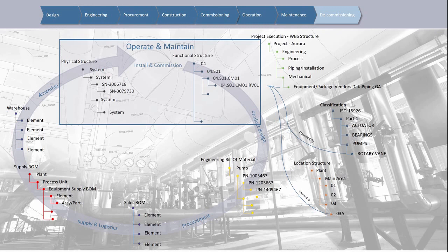Each product delivery undergoes mechanical completion tests to make sure it fulfills the requirements set by the tag requirements, and as the plant is more and more finished, subsystems are tested and undergo commissioning procedures. Then bigger and bigger systems until hot commissioning is performed on the entire plant. All the information represented by the functional structure and the physical structure in the end represents documentation for operation, or DFO for short, and is the basis from which the operator can operate and maintain the plant in a regulatory compliant and safe manner.